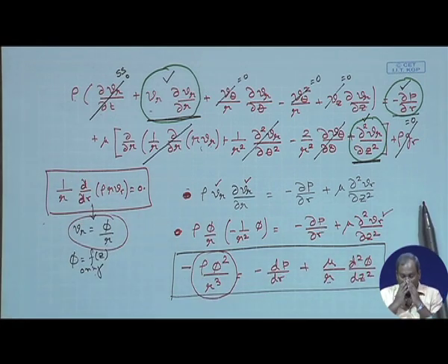But if we try to think about the genesis of this nonlinearity, then probably it would give us some idea of some asymptotic condition in which the effect of this nonlinear term would not be significant. So, if you again look at the derivation, you would see that the nonlinear term arises from the left hand side of the Navier-Stokes equation, and the left hand side of the Navier-Stokes equation, as I said many times before, is due to the convective transport of momentum.